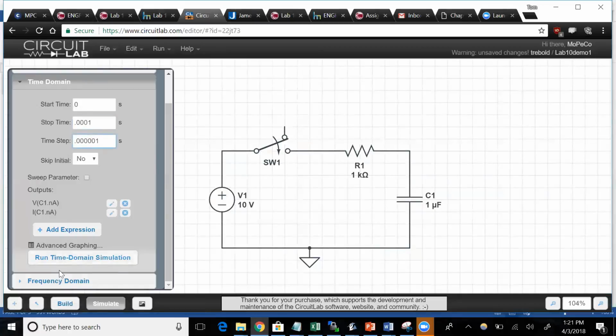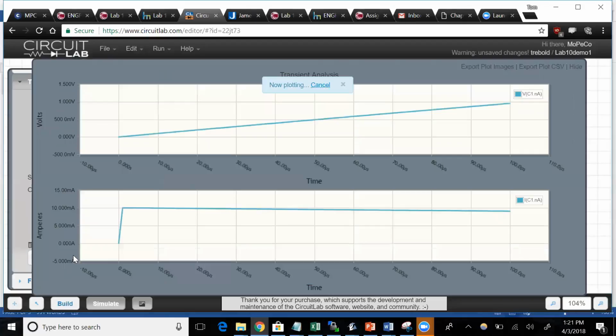what does that mean? What does that mean if you see a transient curve that's a straight line? Mason, you were going to say something. Yeah, you didn't extend the time window far enough to see the full transient response. If you get a flat line, it means your estimate of the time constant is way off.